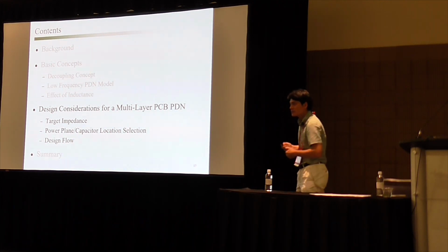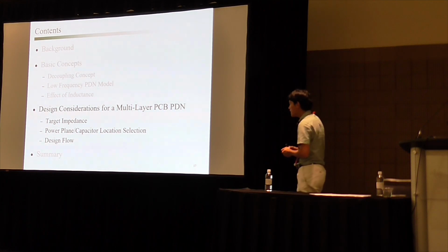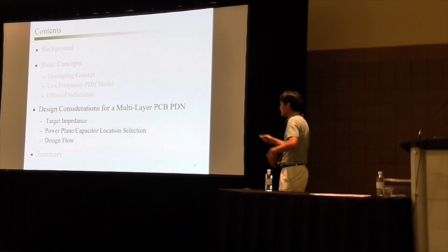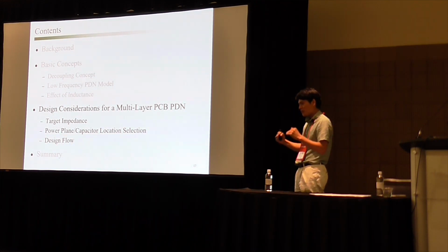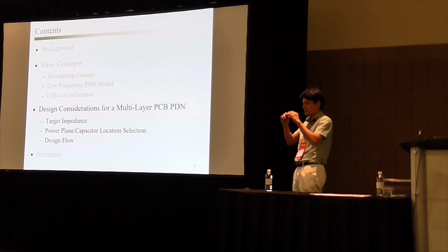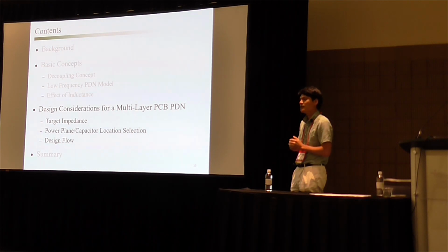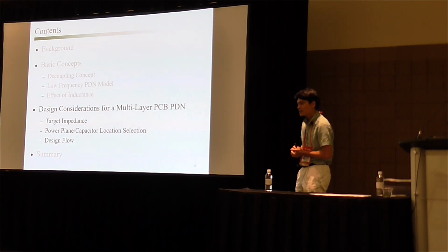On your circuit, you showed that 200 picofarad that had no inductance. It seems to me that's the most effective one for the high frequency. High frequency, I will introduce that later. But the most critical thing is how you connect your power and ground to your package. We haven't considered that here, but at higher frequencies, the most critical geometry is between your package and the power ground plane, how you connect these two. And these things can be treated relatively simply for low frequency.